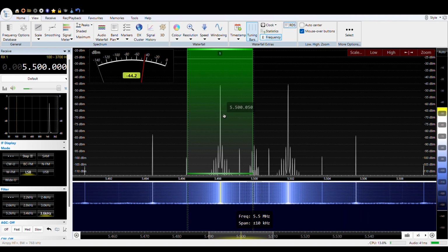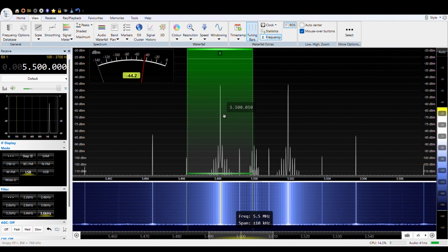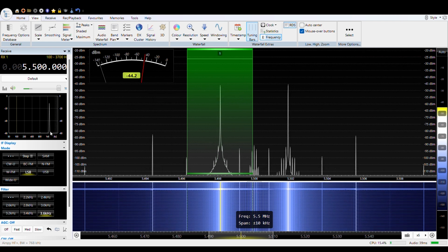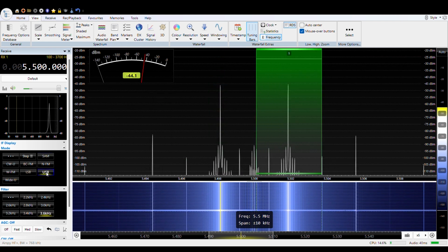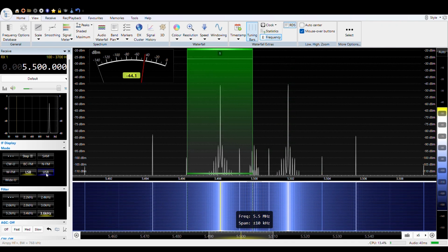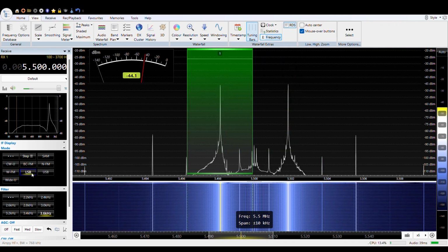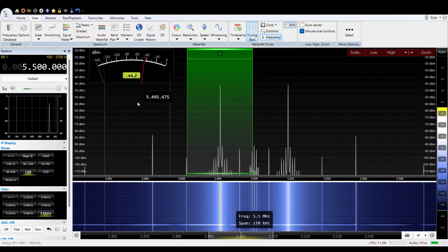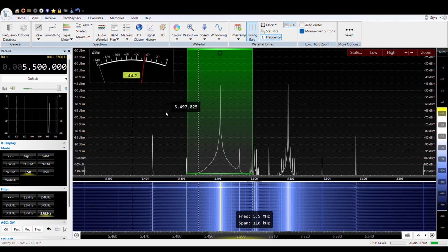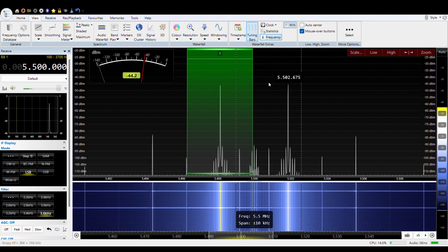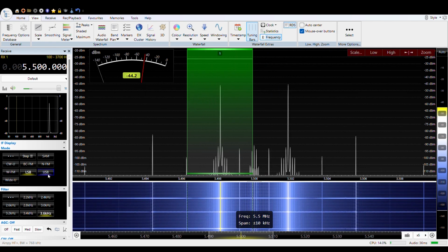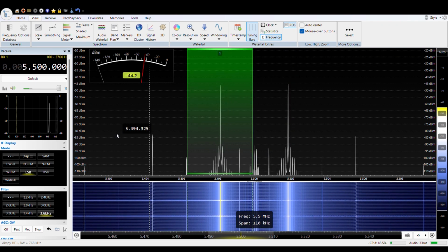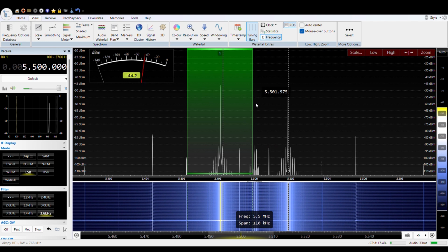And bingo. We're listening to that lower sideband signal at 1890 hertz, 1.89 kilohertz, coming through. You can see it over here on the IF display. You can also listen to it on upper sideband, and there's a very slight shift in frequency there, and that's to be expected because my signal generator frequency doesn't perfectly match 5.5 megahertz exactly the same as the AirSpy HF thinks it is. But nonetheless, we got lower sideband, upper sideband, exactly as expected from a double balanced mixer.